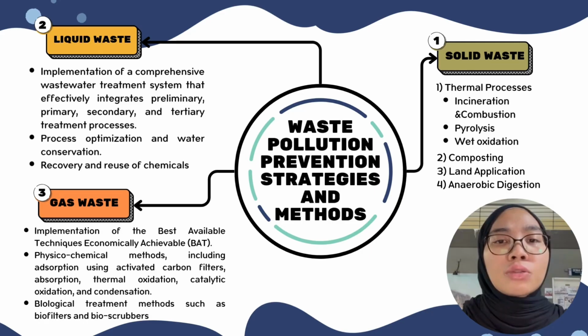In addition to this treatment, industry can adopt supplementary waste prevention strategies to enhance sustainability. Water recycling and reuse help reduce freshwater consumption by treating wastewater for reintegration into production processes. Chemical recovery systems such as black liquor recovery allow for the reuse of chemicals, minimizing hazardous waste discharge. Furthermore, process optimization can significantly lower water and chemical consumption through improved operational efficiency.